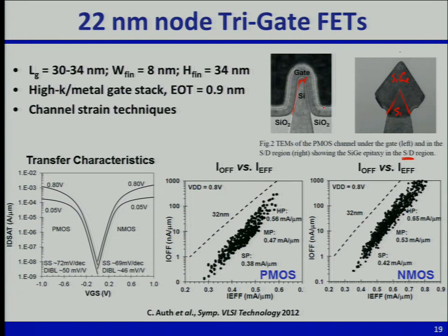And so, you know, etching away a material along the sidewalls is not easy, and then conformally depositing material along the sidewalls, if they're perfectly vertical, it's not easy. So sloping the sidewalls actually helps with the conformal removal of the dummy gate and deposition of a conformal gate stack. Also, if you implant the source drain dopants in the source drain regions, it actually turns out to be hard to dope the fins, somebody did mention. So if you slope the sidewalls, you can actually get more dopants into the fin.